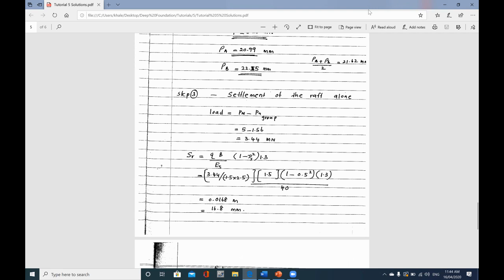So we can maybe fix this thing here. I need you to put between these two brackets, delete this value, and then put 2.5. So that will be 2.5 multiplied by 5 meter, because this is the cross-sectional area of the raft, 2.5 by 5, and that will be as well 2.5, because this is the width of the raft. This is just a mistake in the solution, so I just need to correct this thing here, and everything should be all right.